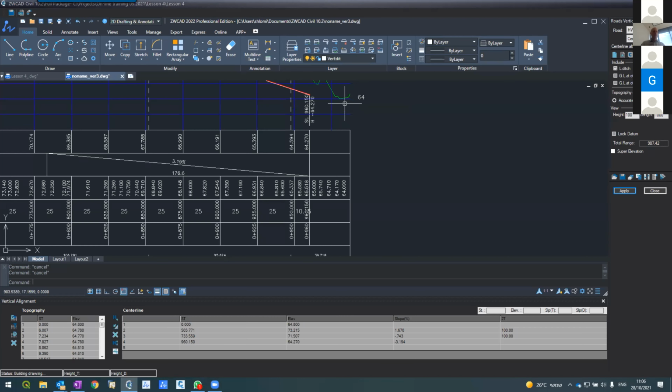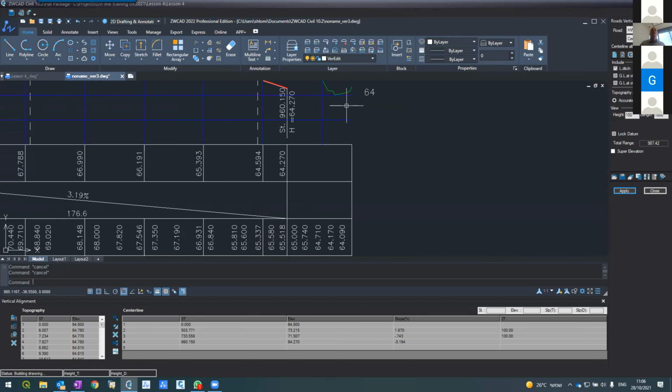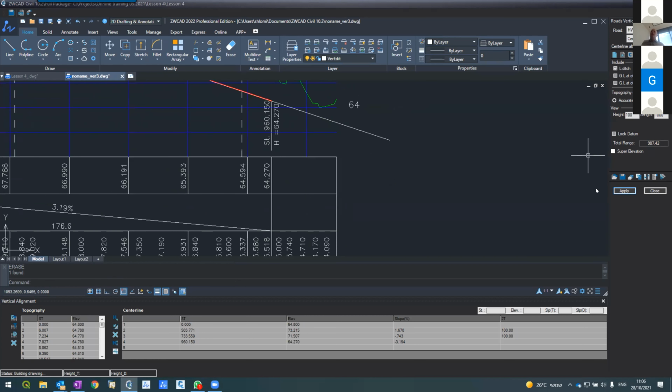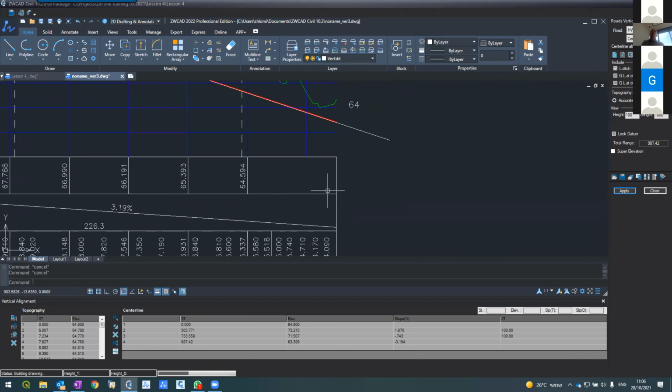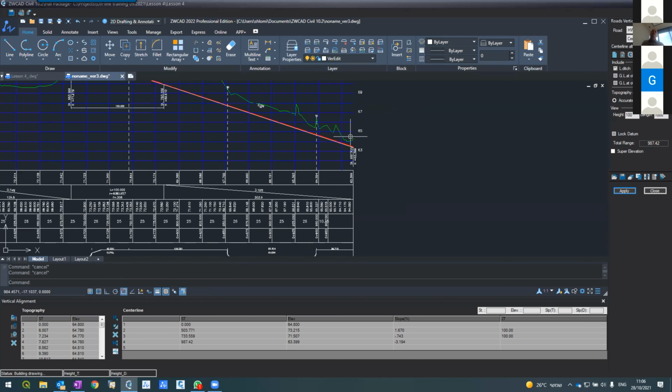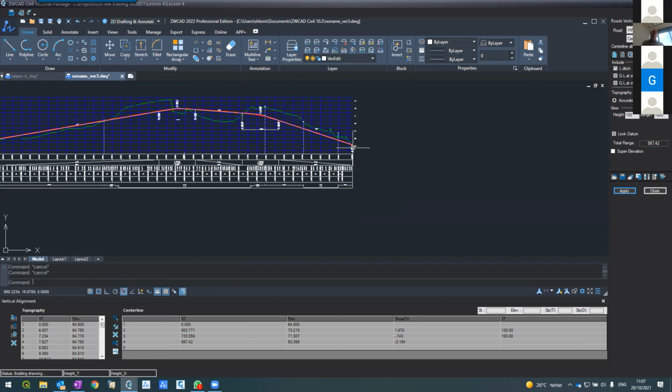What I'll do is very simple. I will do a polyline here. Extend. Okay. So I extended. I can remove this. The var edit up till here, and we press apply. Let's see. And the software automatically cut it at the end of the road. That's it. So now also the profile is okay.